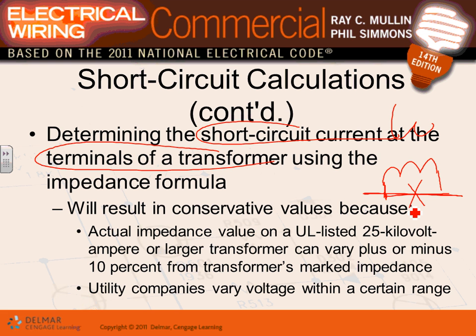You're going to see, guys, transformers have impedances, and the impedance is the only thing between you and that flood of short circuit that's coming from Xcel Energy. For example, if I short the secondary of the transformer, phase A to phase B to phase C, the only thing that prevents me from that flood of current that's coming to burn my building is the impedance of the transformer. The higher the impedance, the more it holds that current, and it doesn't burn me that much. You know what I mean? So the impedance chokes the current that's coming from Xcel, the transmission lines.